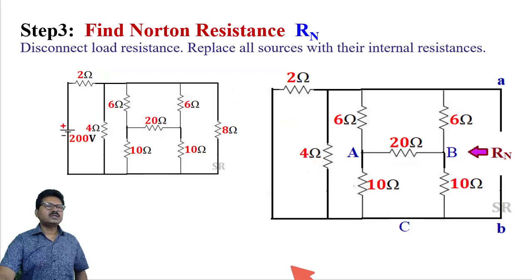Next I will calculate Norton resistance. To calculate Norton resistance, we will disconnect this load resistance and we will replace all the sources with its internal resistances.